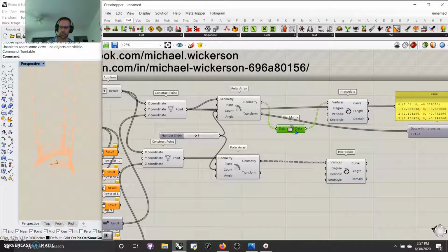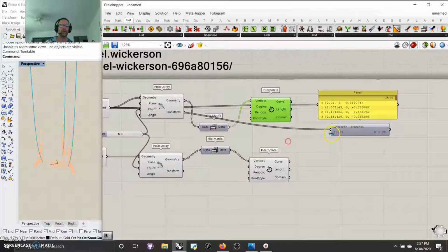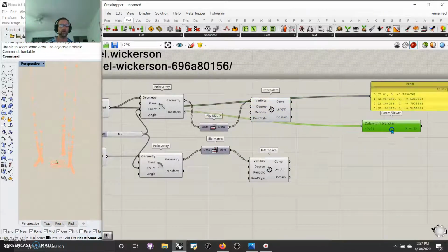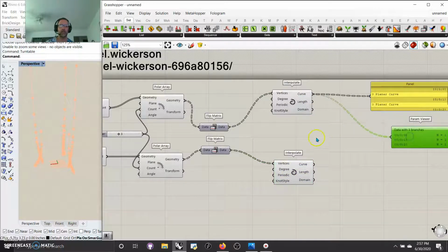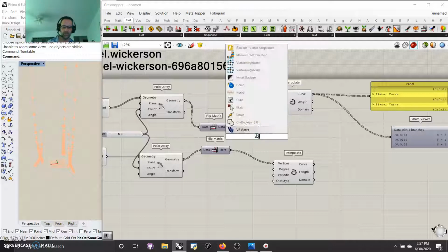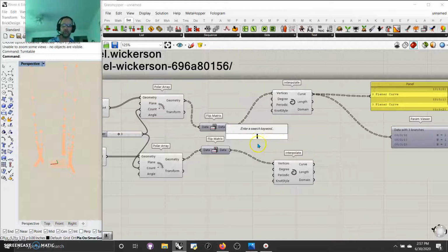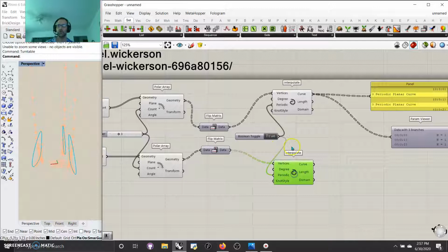And the same thing I'm going to do with another control paste data, and I'm going to interpolate this way. So I got lines going this way and lines going this way. Now these two, very interestingly, once you've interpolated, you can actually take that data, and we'll just keep moving this along so you can see the curves are now curves, and that's how much data we have. I can actually use a Boolean toggle to make these true when it comes to being periodic, and that will close them up. Now I have 3 closed loops and 3 closed loops.